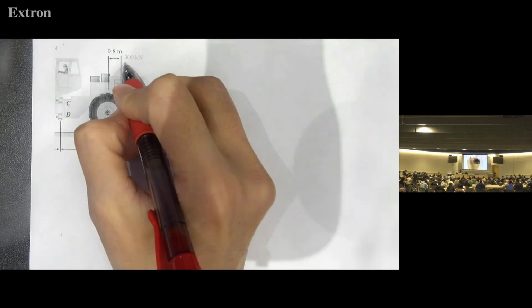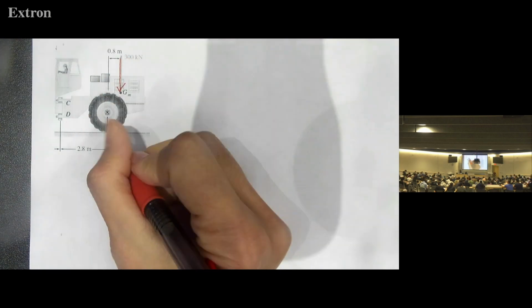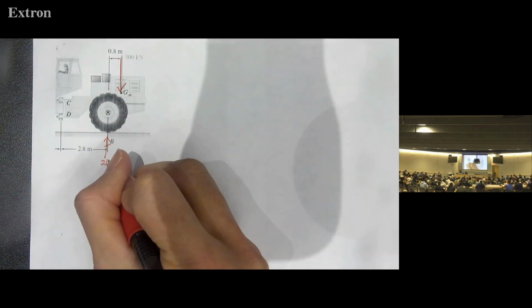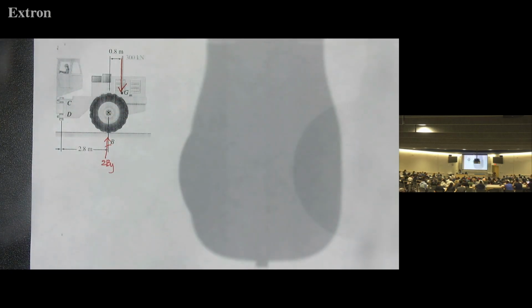Okay, then it's okay to use this one because we already simplified a lot, extremely simplified, so we now can see this one is just 1 bar, right? And we have 300 kilonewton here at G, M here, and then we know the distances, and also we know 2BA, so that's 2 times 162.5, right? So that's 2BA, and then now what kind of force do we need to define? So that is the problem, okay?